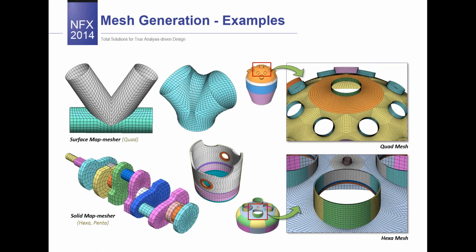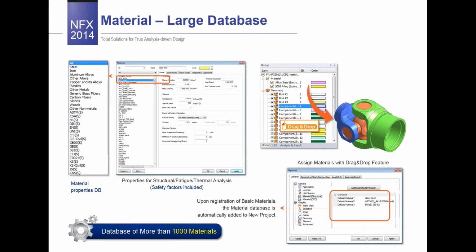So we can, let's say, split our model into a few parts, and some parts can be meshed automatically, while some parts of our model can be meshed using manual methods or techniques. This kind of high quality mesh, as you see on the slide, will assure high quality of the results without any doubts about internal discontinuities or, let's say, bad quality elements, which is very important for FEA analysis.